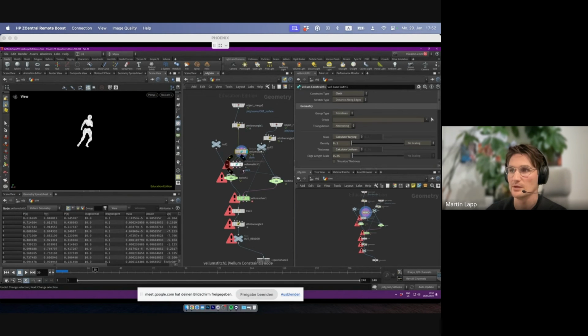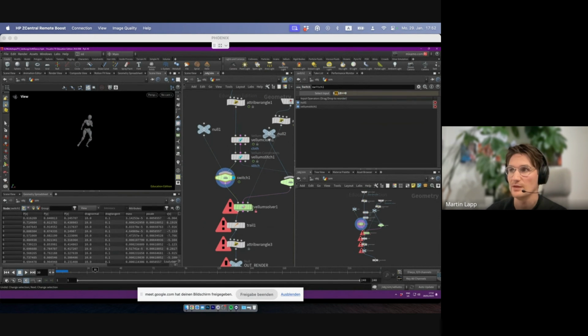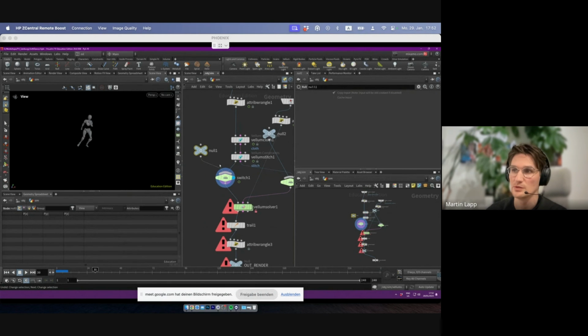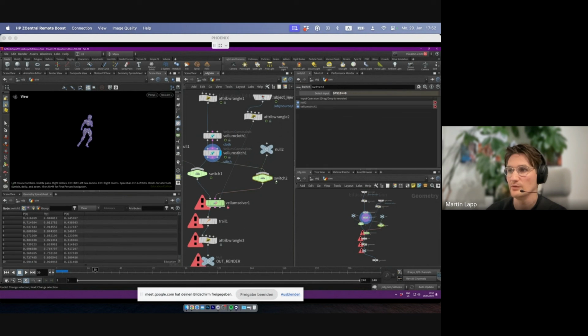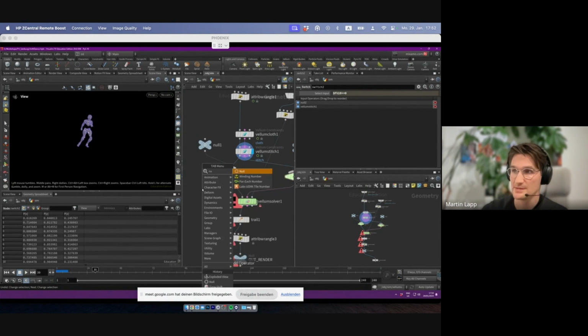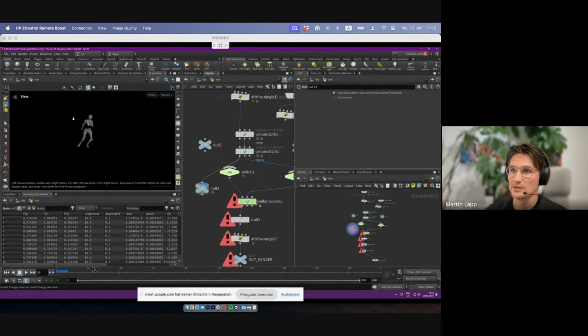Then this gets created into a vellum object with the constraints. And this switch does the same trick again. It says every 10th frame, you switch between nothing and this object. Here I do the same. So the only difference is that this vellum stitch node has multiple outputs. This one is the geometry itself that we're looking at, and the second one is the constraints that it created.